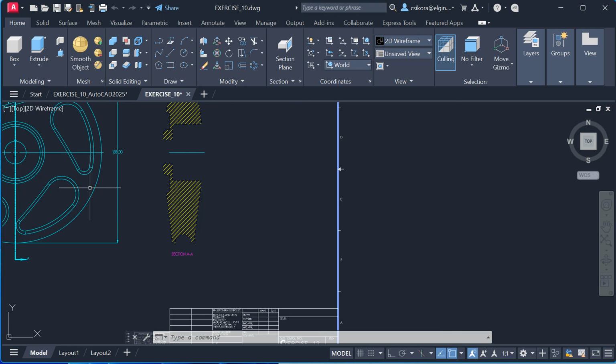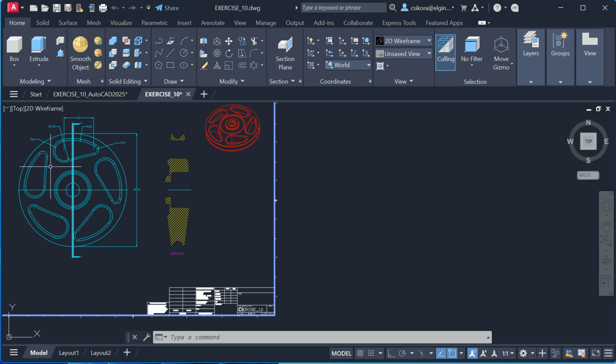I specifically changed some of the colors of it so it was easier to see. And we have a wheel and we have some dimensions. There's some cutouts in there. We see an isometric view up in the upper right corner, and then we see the section view based off the center. Now you can see the top part of the section view actually has a pocket in it, or a hole, for this opening. The bottom actually is a nice clean cut through, so there's no interference.